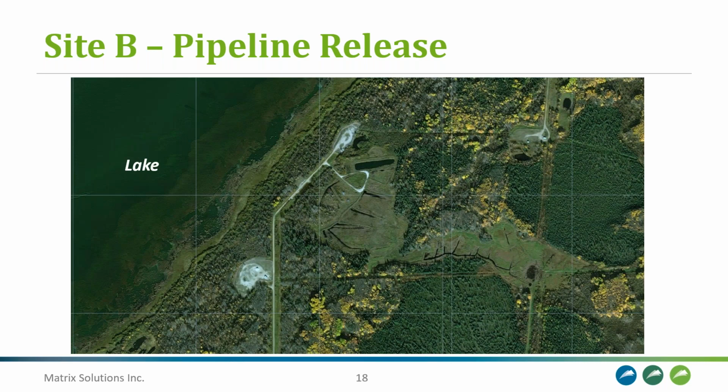And as you can see, the site is located near a large lake to the northwest, and the surrounding land use is natural area. So initial spill response consisted of fluid recovery, about 16,000 cubic meters, and local hotspot soil excavation that amounted to about 13,000 tons of soil.